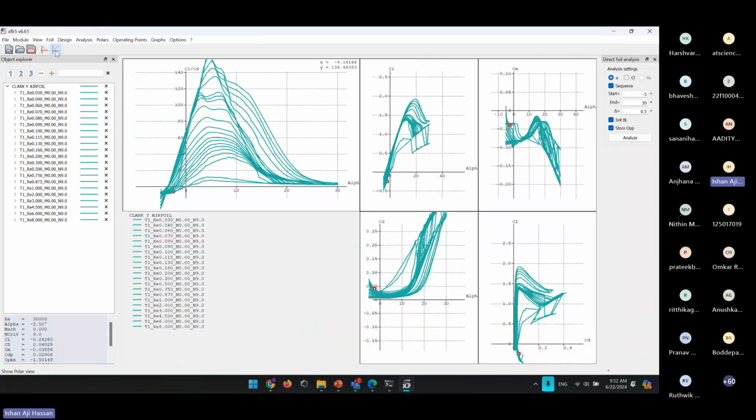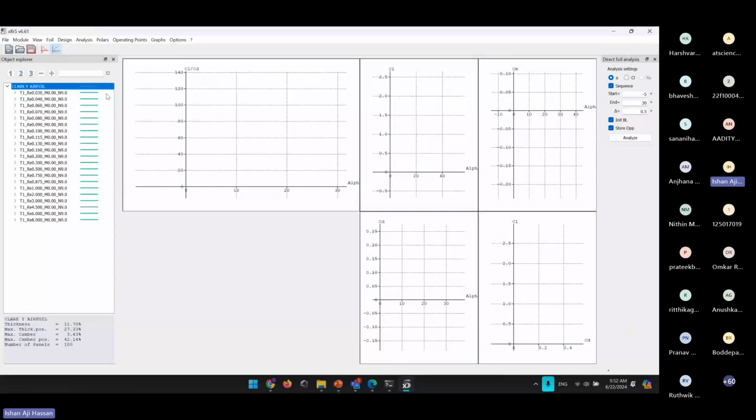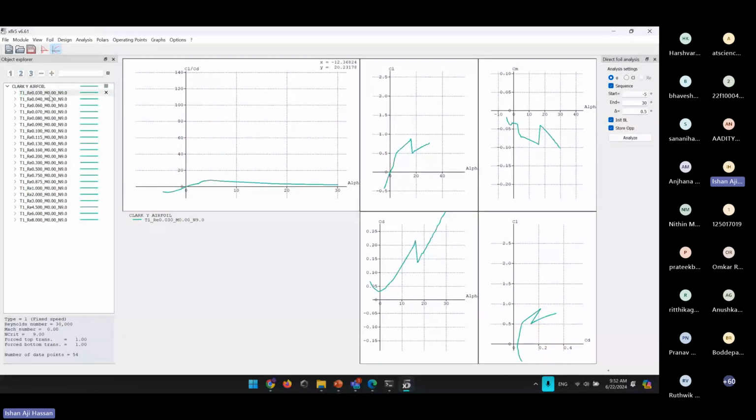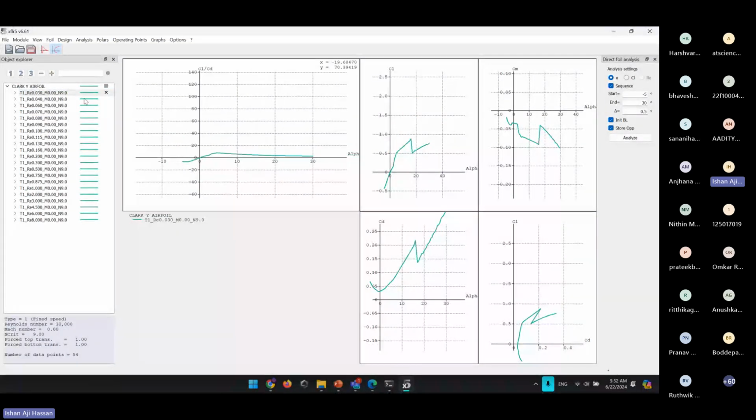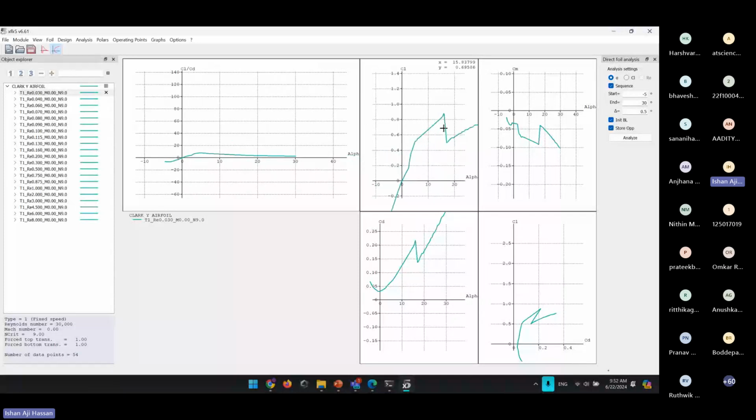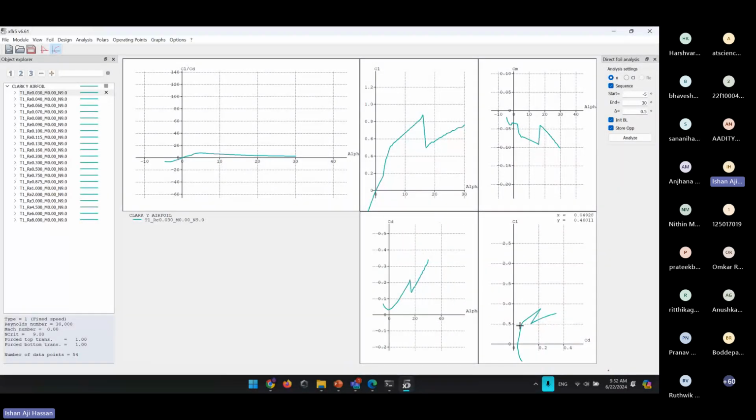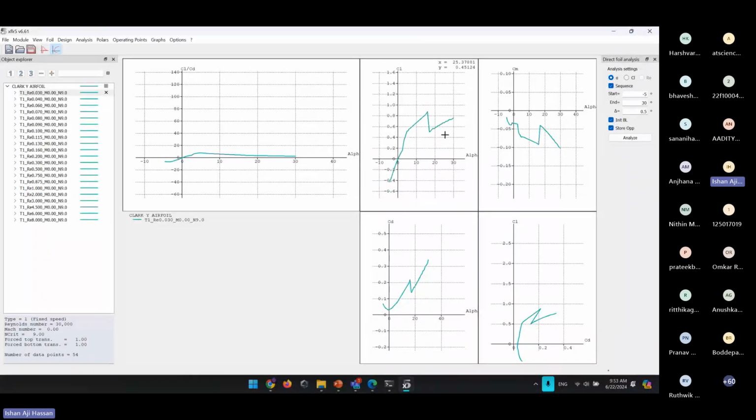If you remember, I told you earlier how the lower Reynolds numbers can get a bit janky. I can show you here, this is the curve for Reynolds number equals 30,000. You can see it's not really exactly as we expect. There are some unconverged points in between. That is what these straight lines are, because it's just jumping from one point to the next. So it's not ideal to use such a low Reynolds number. You should go into the millions.